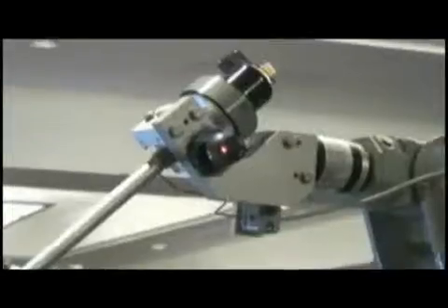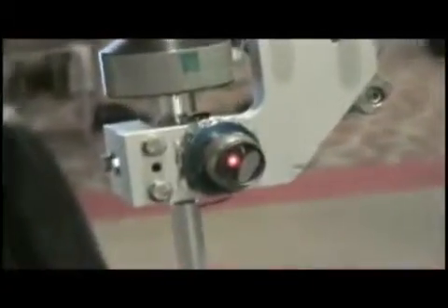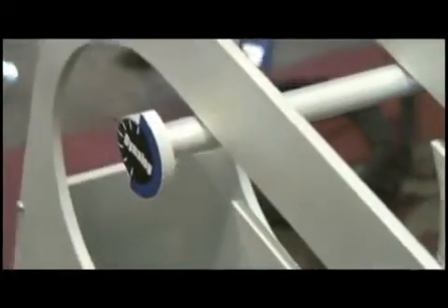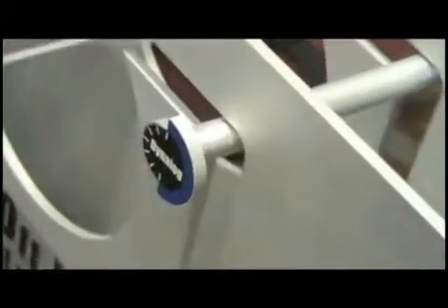One of the main benefits that integrators and end customers get from doing this type of process is that they decouple, or remove, the programming process from the critical path of launching a robotic system. What this means is that they can do the programming far in advance of the actual robots hitting the factory floor. Of course, when the robots are installed on the floor, the timing of this process is very critical. So if you can have all your programming done ahead of time and your robot calibration work done ahead of time, then installing the robots and getting the project up and running quickly can be done in as little time as possible.